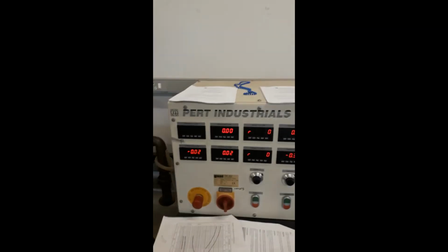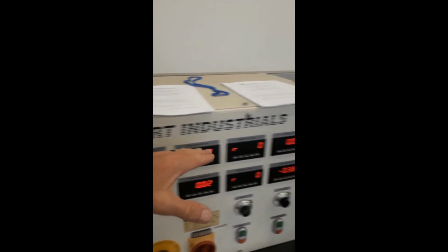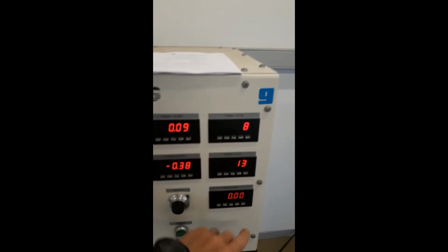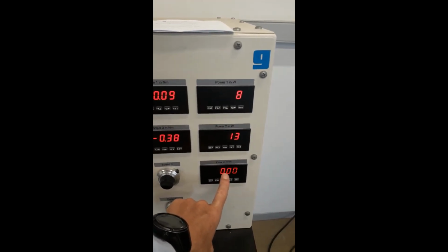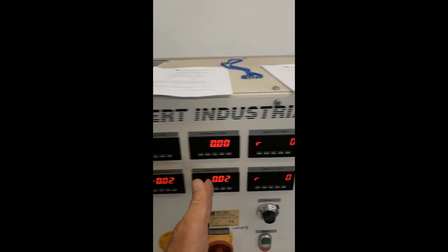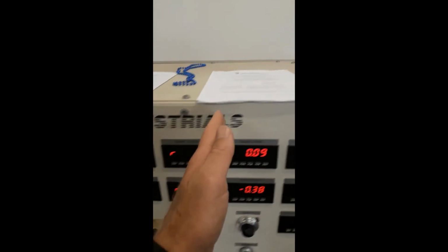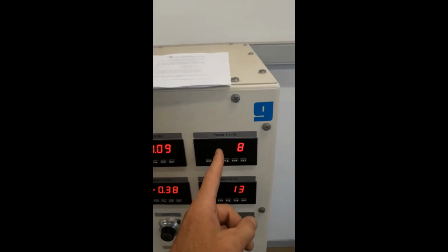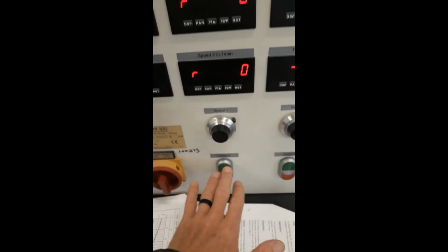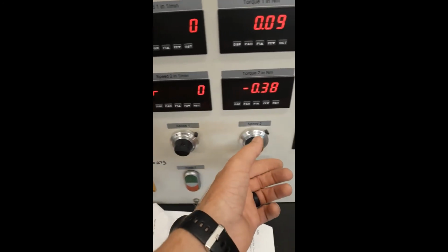Then the control panel. The top numbers is for pump number 1 and the bottom numbers is for pump number 2, and this one sitting here by its own is the flow meter, because we only have one. Then this is the inlet pressure, that's the outlet pressure, that's the pump speed, this is the torque, and this one is the electrical power in. Also we'll have here the on-off buttons for pump number 1 and pump number 2, and this is a variable speed drive, so we can adjust the pump speed for both pumps.